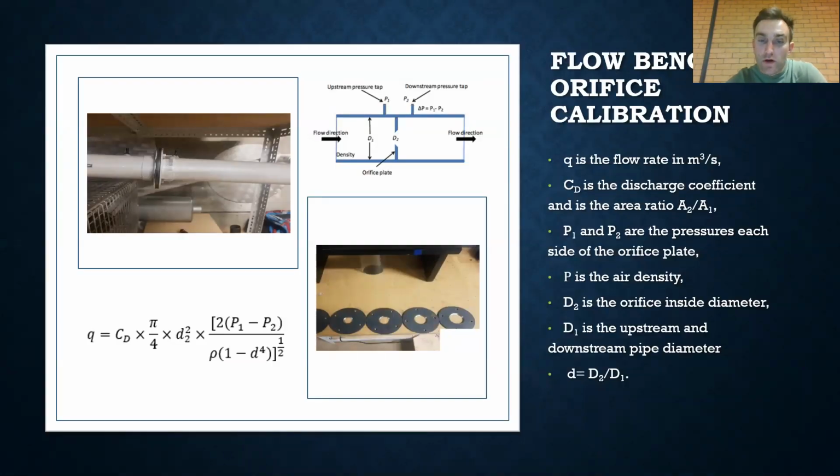To measure the mass flow rate on the flow bench, the equation seen to the left is used. This equation uses the orifice method to measure a pressure drop over a plate with a hole in it. The orifice is located in the draw pipe that draws the air through the test piece on the bench. Depending on what the expected flow rates and the scale of pressure drop you want to work with determines the size of the orifice plate. These plates start at 15 mm and step up to 35 mm in 5 mm increments.